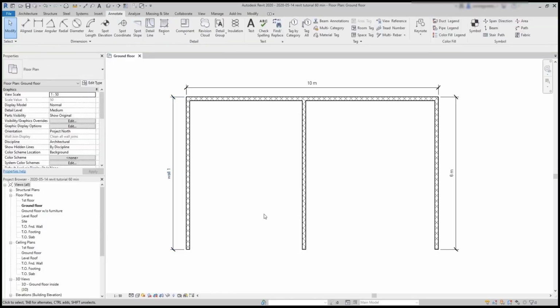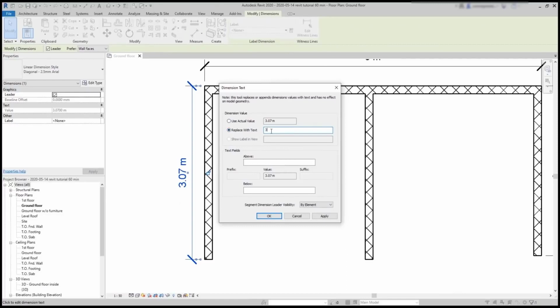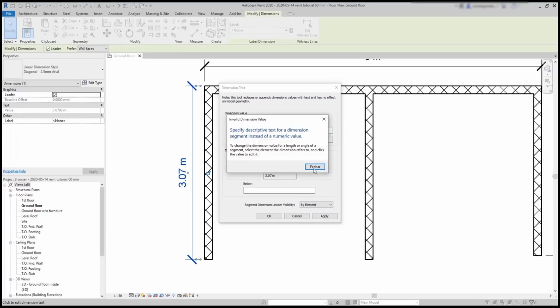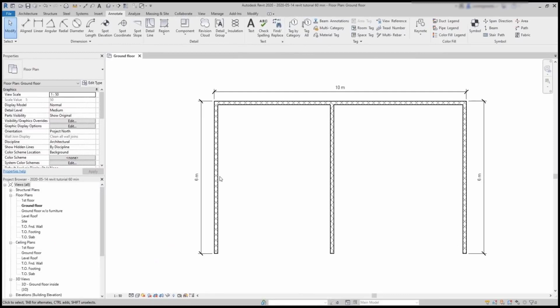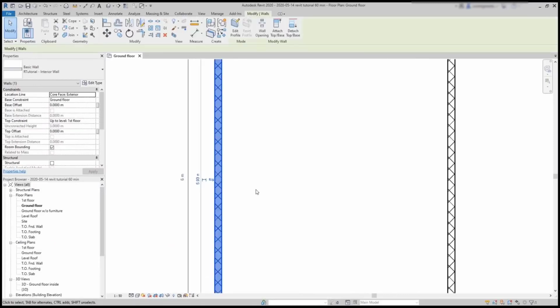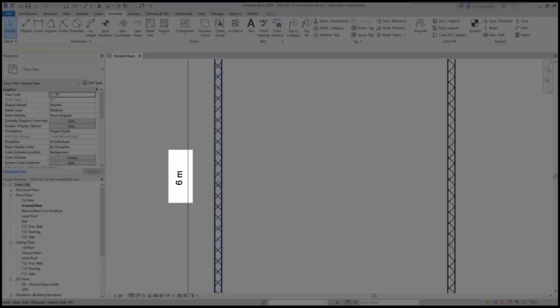But keep in mind, if I want to cheat or just change the actual value to an approximate number, the program doesn't let me do it. It says that I cannot replace a value with a different value. Basically, to modify the length of this wall, I have to select the wall first and then click on the dimensions in the same way that I do for the temporary ones. Notice also that when the dimension is editable, the color changes to blue.